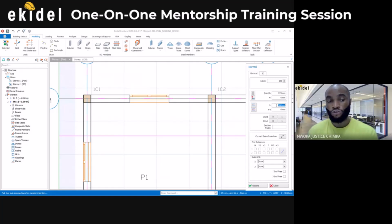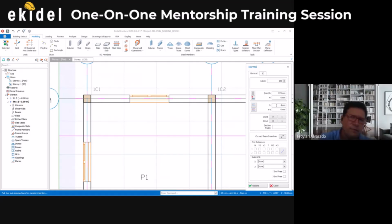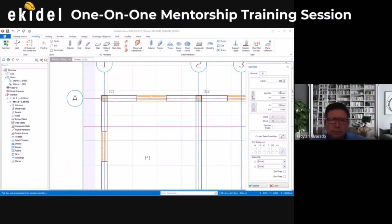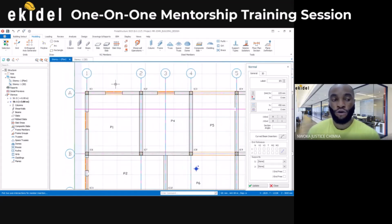But no, you need to add the slab depth to it. Well then it would be an additional 150, that's like 450. Exactly. So now, once you have added your width and your depth, when you want to insert, you might be seeing a warning from the code that the section you're choosing is small. You can choose to ignore it after the design. If it's small, you can then choose to increase the size of the section.